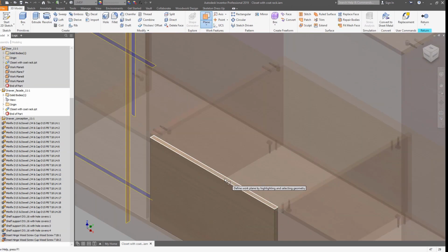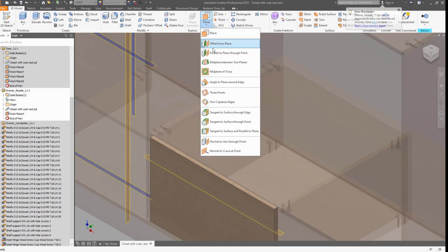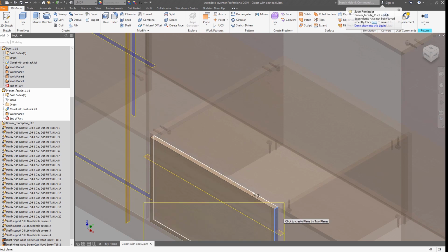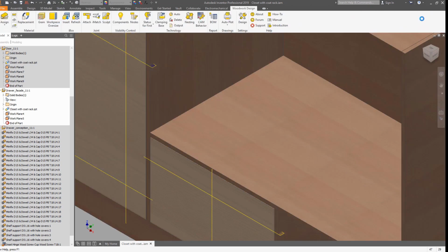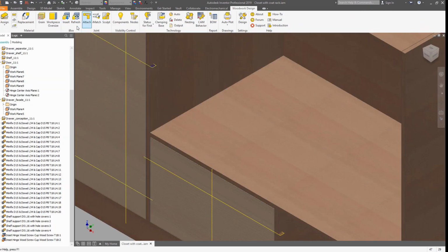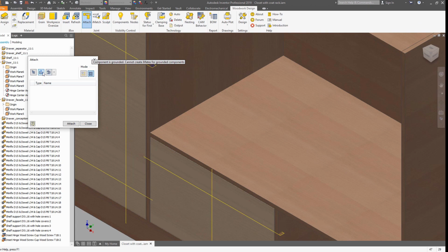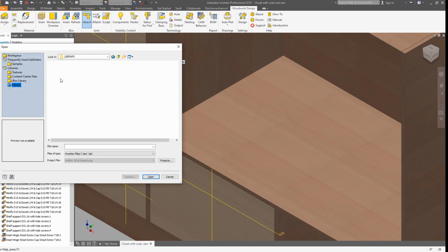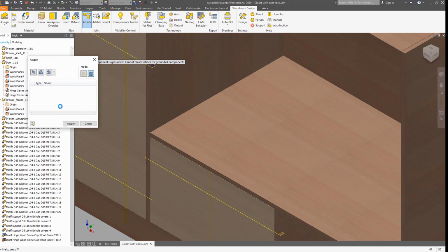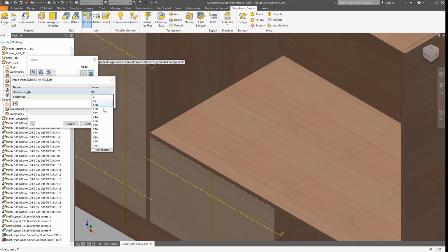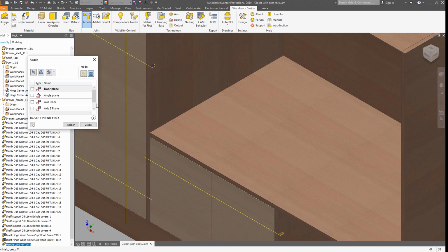Now let's deal with the facade of the door. Again, the position of the handle can be defined by 2 work planes. One is in the middle, the second one defines the horizontal offset. Once it's done, we can use the touch command again to browse through the library structure in order to find handles. Choose the appropriate length you prefer,